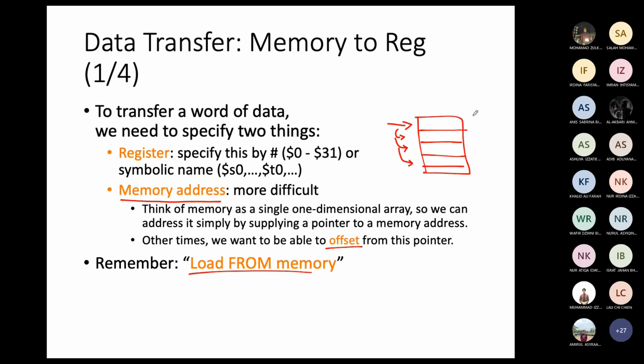So let's say the memory address starts at 0. This one is in bytes. Remember, it is in 4 bytes, 4 bytes, 4 bytes. So 4 plus 4 is 8, and then 8 plus 4 is 12, and then 12 plus 4 is 16. So remember, it is in 4 bytes. 1 byte is equal to 8 bits, so 4 bytes means 32 bits.